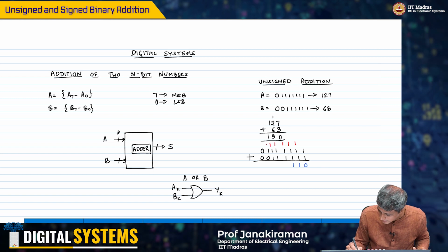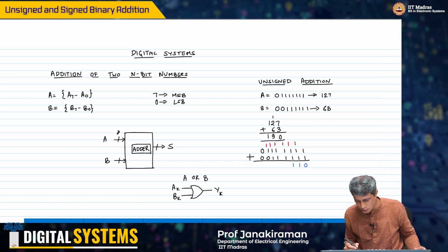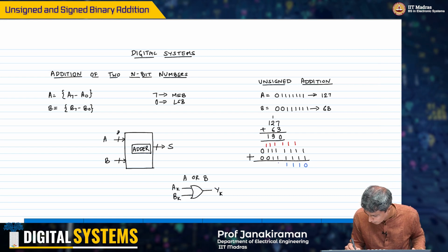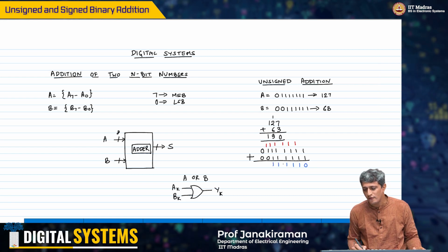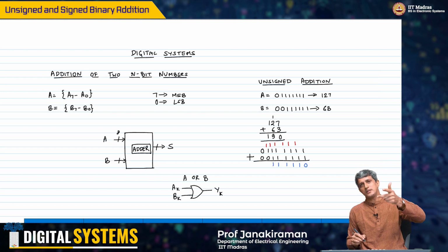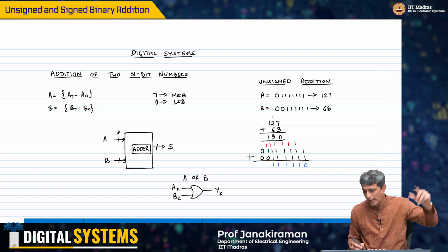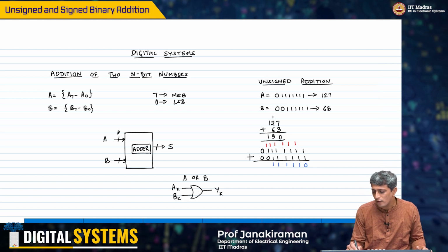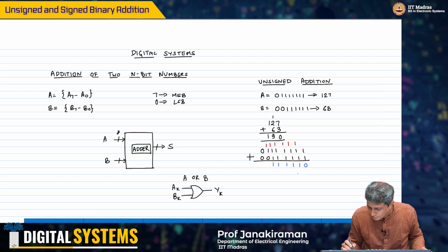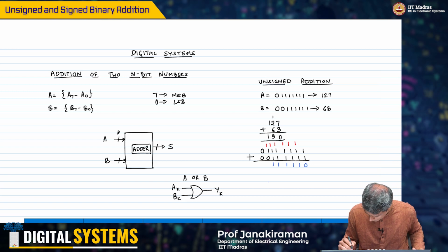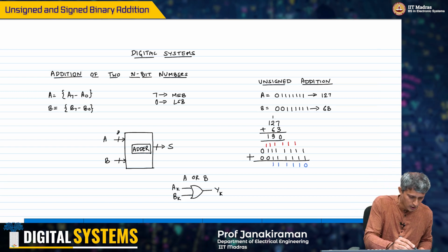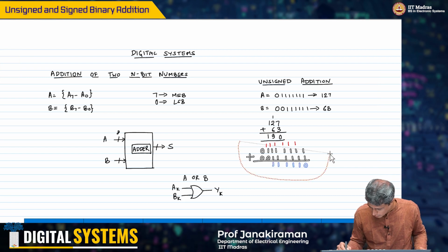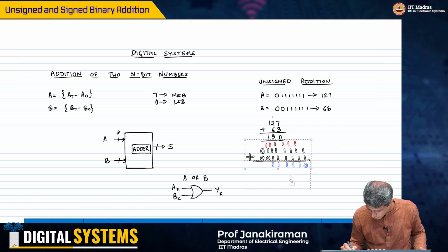That same thing is actually going to continue, so I am going to just put it until where it is supposed to happen. Everywhere you see addition of 3 ones, the answer will be 1 and a carry of 1, so you take the carry and keep propagating it like that. Let me move this a little down so that I can represent the bit position also nicely.